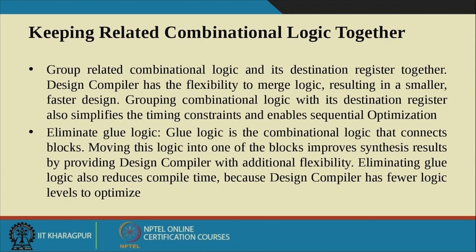Design Compiler has the flexibility to merge logic, resulting in a smaller, faster design. Grouping combinational logic with its destination registers also simplifies the timing constraints and enables sequential optimization.